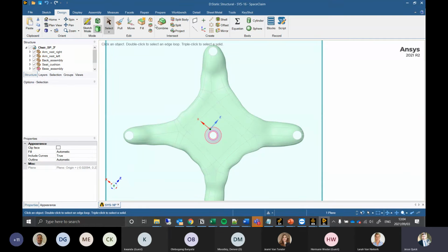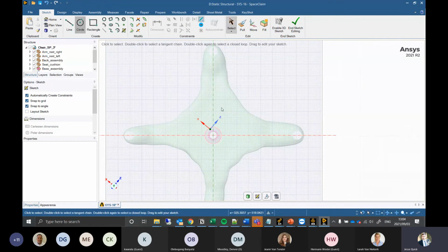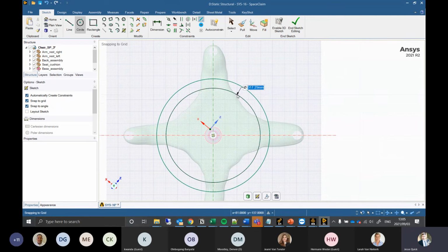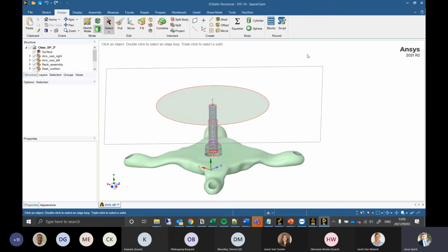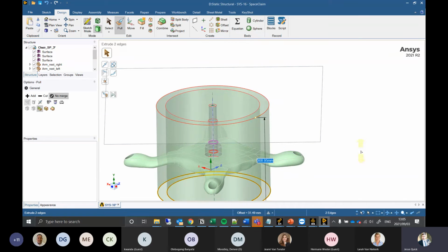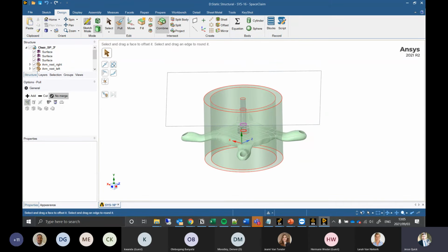As I mentioned, we're going to have two separate cutouts. The first thing is I'm going to select sketch mode, then create a circle over there, pop it in, and then create another circle, maybe over there. Now we're going to be looking at this region for our submodel. If I go to the 3D view, I've just got to take that edge and pull them, no merge, in this direction, and then take them through over there. Okay, great, that's what I wanted.